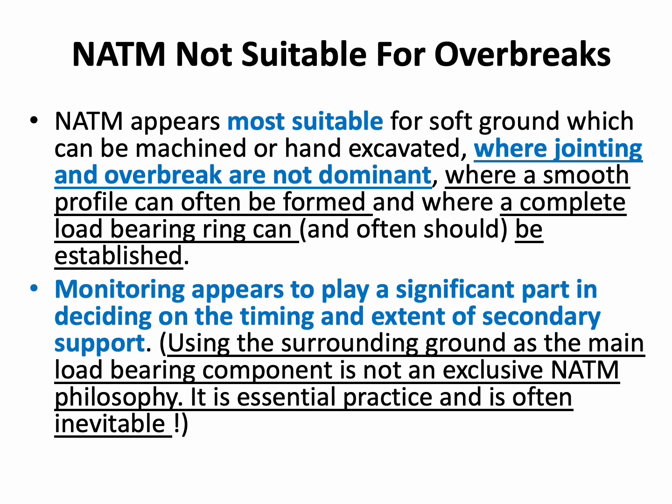NATM appears most suitable for soft ground, which can be machined or hand excavated, where jointing and overbreak are not dominant, where a smooth profile can often be formed, and where a complete load-bearing ring can and often should be established. Monitoring appears to play a significant part in deciding on the timing and extent of secondary support. So monitoring becomes very important, and this decides timing and extent of secondary support.